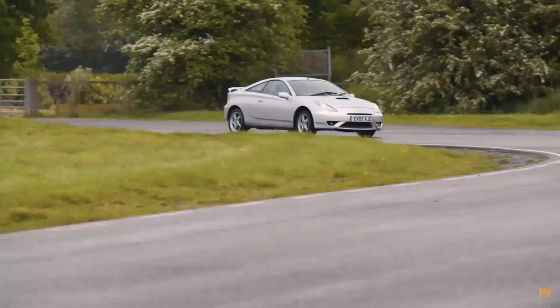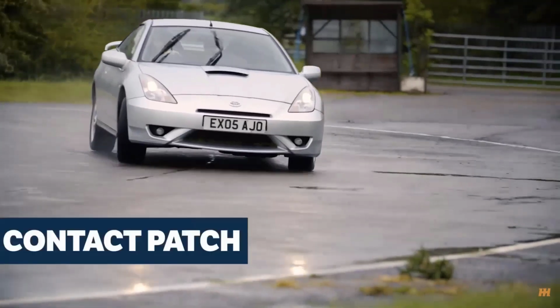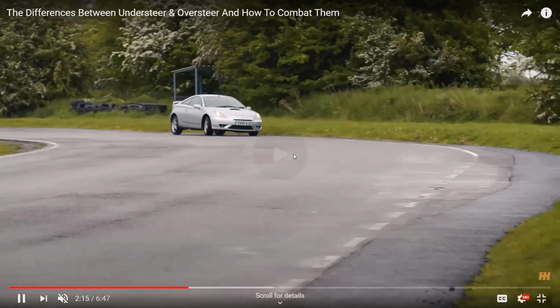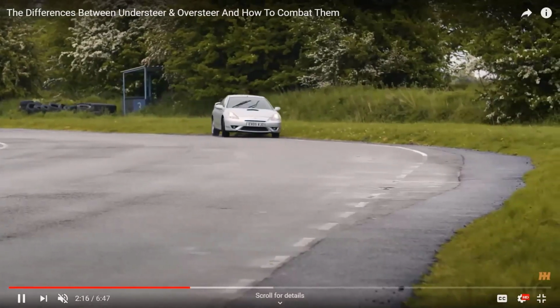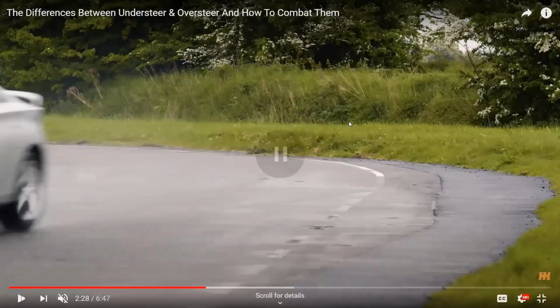So this is what we need to do. This is what an experienced driver will do while driving the vehicle. But in our daily situation, an inexperienced driver can't do this. These things will be taken care of by the vehicle dynamic controller by applying the brakes. Whatever is required, it will apply the brakes. See, because of understeering, he is lifting the throttle, so it tends to oversteer and rotate. So he is removing the throttle and making a change in the steering, so now he can make the turn smoothly.